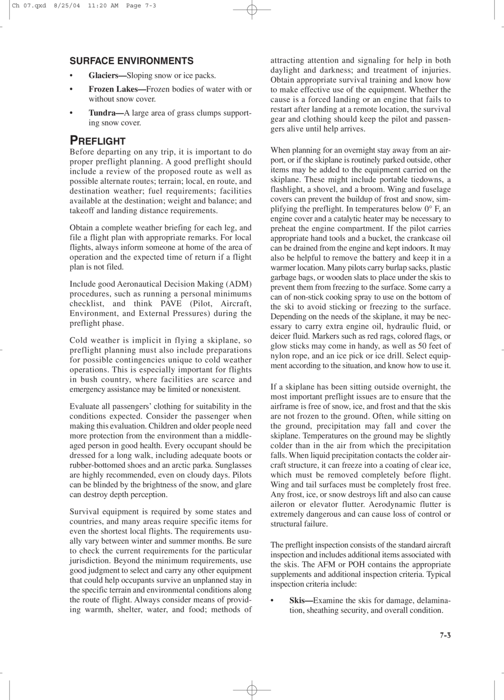For local flights, always inform someone at home of the area of operation and the expected time of return if a flight plan is not filed. Include good aeronautical decision-making, ADM, procedures, such as running a personal minimums checklist, and considering pilot, aircraft, environment, and external pressures, the PAVE checklist, during the pre-flight phase.